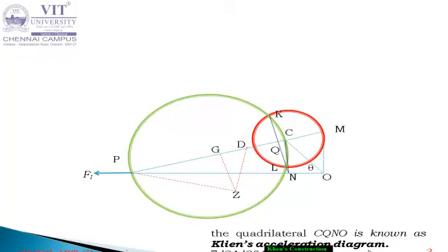If you are not able to understand why we have to extend this line up to this point, what you can do, use the relation. Somewhere we don't know the G, so we have to find out the distance. Use the same relation, Pc divided by Pg, that will be given in the problem. You can measure this height Cn, by which scale you have drawn or taken. From that scale you can fix this.